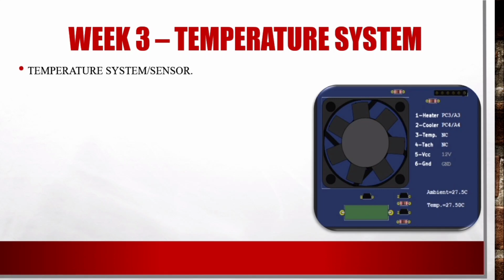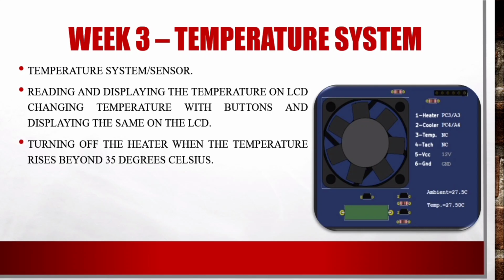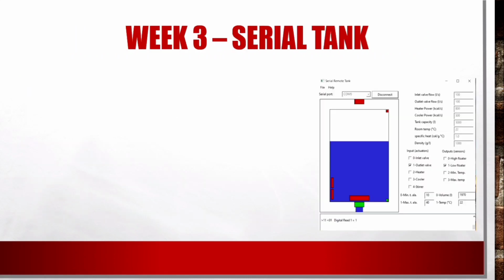Next one is the temperature system. The temperature sensor is used for reading and displaying the temperature on the LCD, changing the temperature with buttons and displaying the same on the LCD. Turning off the heater when the temperature rises beyond 35 degrees Celsius, displaying that the heater and the cooler are on on the LCD, reflecting the same on the Blynk IoT mobile app also.